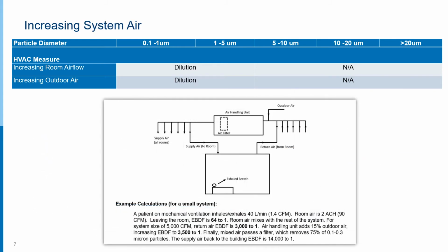So what about 100% outside air? That's very common in Europe. It's not so common in the United States, although some of our systems have economizers or they can be converted to 100% outside air, weather permitting. I've encouraged engineers to think about this in terms of dilution factor. It's kind of a simplistic idea, but I found it to be very useful when talking to our clinicians.